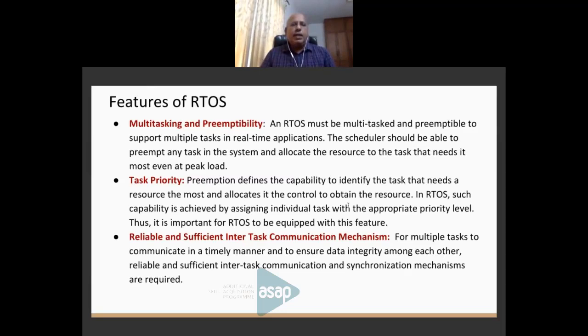But multitasking basically is, instead of writing a monolithic, long program from top to bottom in a linear fashion, you are dividing it into multiple chunks so that they can be executed in parallel. This concept of parallelism, that also I'm going to explain as we proceed. But once you split a large application into multiple tasks, all these things are called tasks, and we have to give different priorities. Not all tasks in all these embedded systems have the same priority.